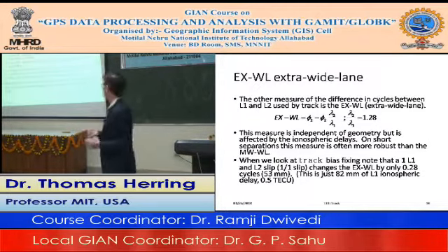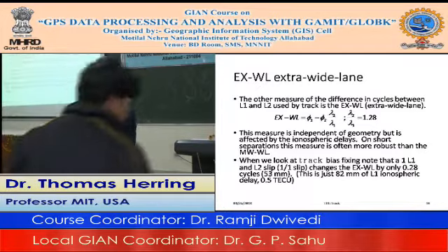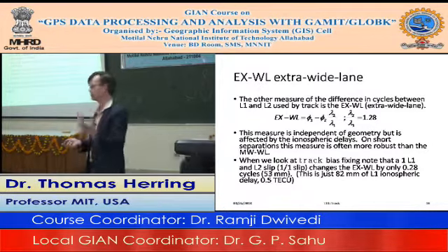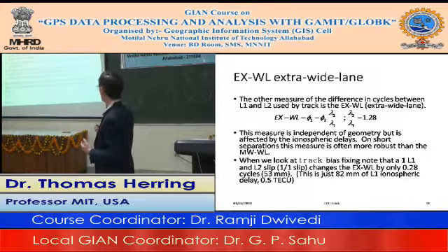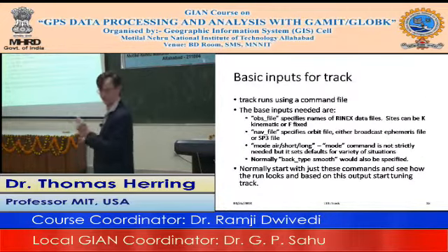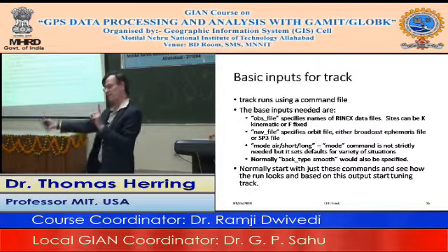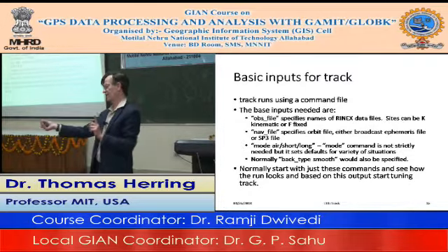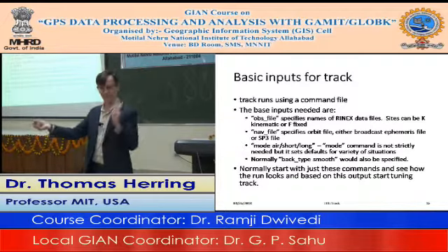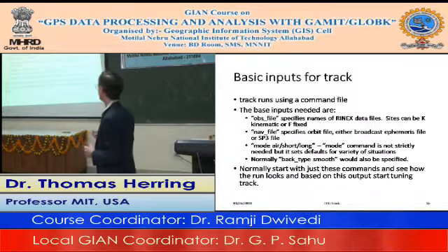But when you run track, the big one you have to use is a command called obs file. That's where you name the RINEX files that you want to process, and it runs directly off RINEX. They're designated either as K for kinematic or F for fixed. We recommend you should only have one fixed site. If you have another base station, you treat it as kinematic, but you give it 0 process noise, so it can't move. That's the better way to do it. So you have to tell it that.